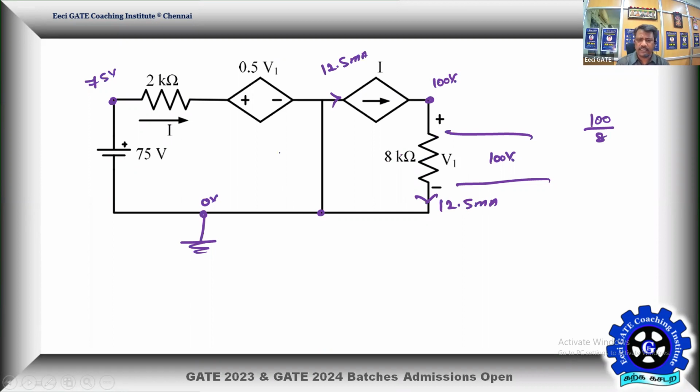So here also you are getting the same current I. We'll check whether this current is also going to be the same, 12.5. It has to be because this is given as I, so this current magnitude should remain 12.5. We'll prove it. So this point potential we know already 0. Half of V1, 100, will be equal to 50 volts. So this is also going to be 50, because it is 0, potential rises by 50.